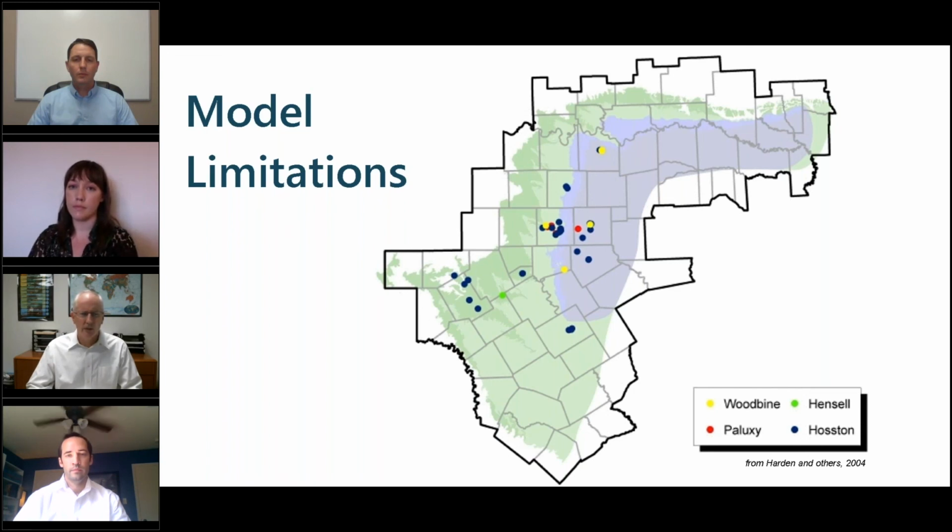One of the big issues in Texas that we have is the uncertainty in historic pumpage. That's a huge issue because that pumpage has such a significant impact on the resulting groundwater model and how you're trying to calibrate your model. These data limitations may also limit your understanding of the aquifer and the conceptual model you put together of aquifer flow, how the aquifer functions, how the different boundary conditions play in there. The lack of the data may limit that conceptual understanding of the model.